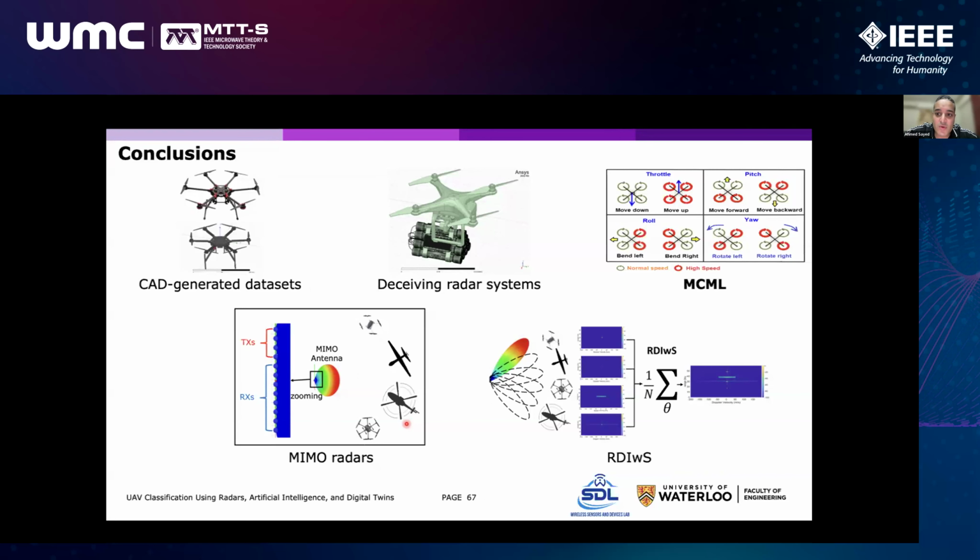We proposed a mechanical control-based machine learning method to enhance the degraded classification accuracy in case mechanical control information of drones wasn't taken into consideration. The importance of using MIMO radars was investigated. The impact of antenna field of view on the classification accuracy of drones using MIMO and SISO radar systems was investigated. Also, the topic of multi-UAV detection and classification was covered. Also, we proposed a range operator integration with steering beamforming based method to overcome the limitations shown when using only the MIMO case.